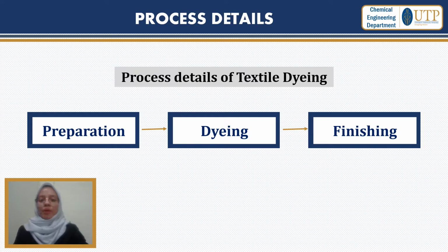So preparation is the process of removing unnecessary impurities from fabrics prior to dyeing. Cleaning can be done in this step with aqueous alkaline substances and detergents or enzymes. Bleaching is also done in this process, which is an important step after the cleaning process. There are three technologies used in bleaching, which are sodium hypochlorite bleaching, hydrogen peroxide bleaching, and sodium chlorite bleaching. The standard chlorine dioxide concentration in bleaching effluent is 10 to 200 mg per liter.